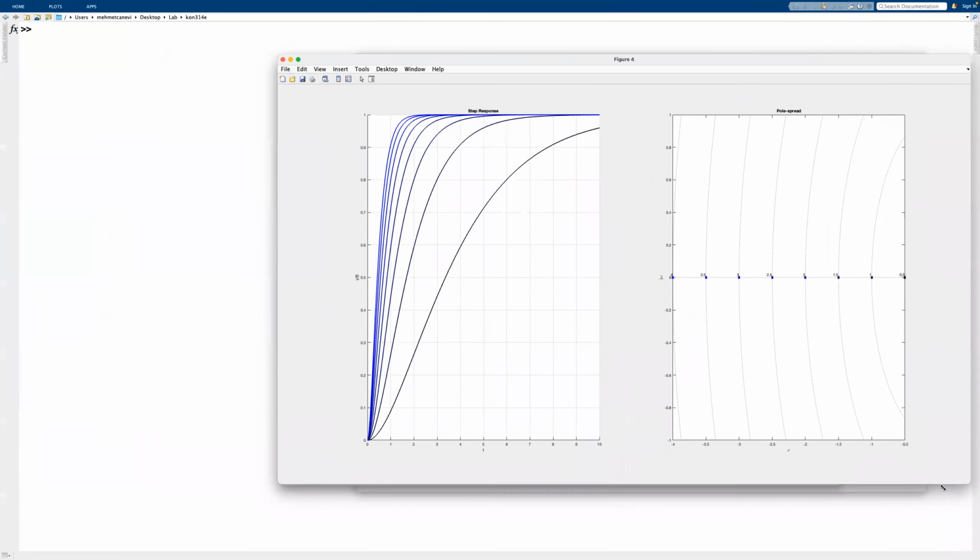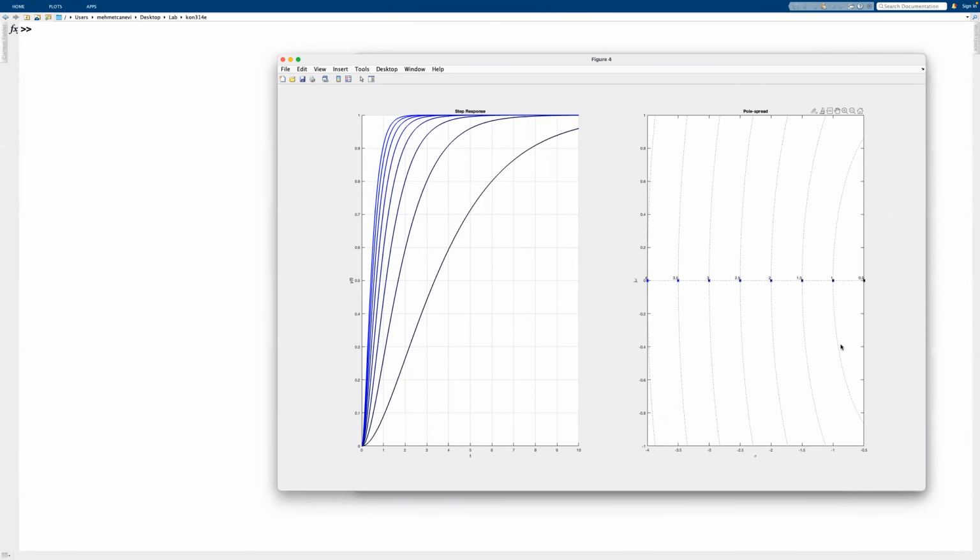Now, again, we have basically this first order system behavior. Because zeta is equal to 1, we have a critically damped system. And yeah, if we increase the radius of omega n, or omega n for short, then we see that we are going to the left. Therefore, the brightest one is the fastest one. The darkest one is going to be the slowest system. So the system speeds up, but the behavior stays the same. It's just a sped up version of it and nothing else.